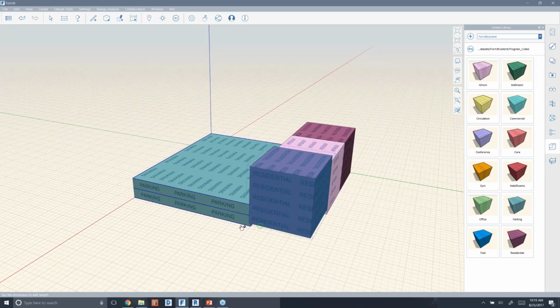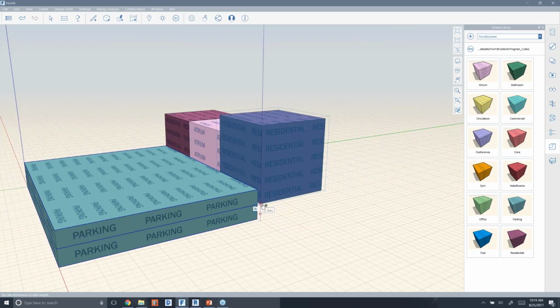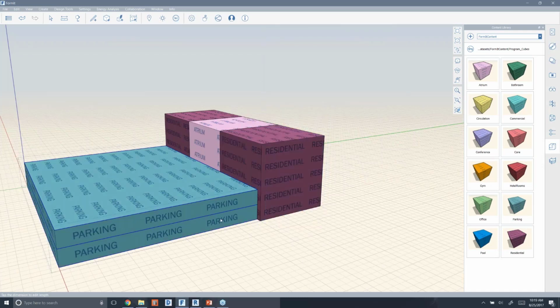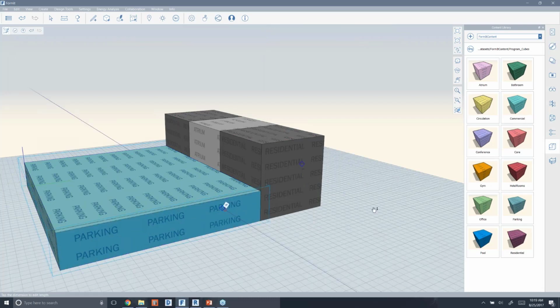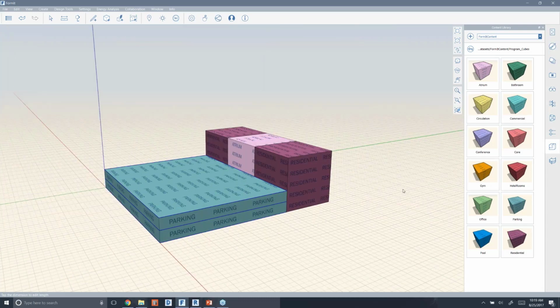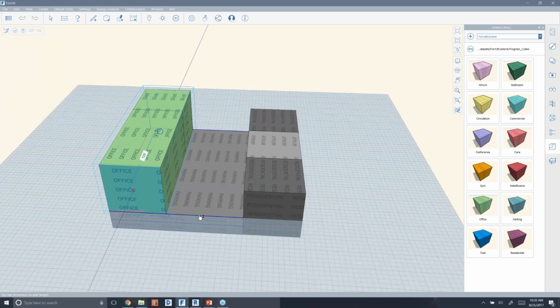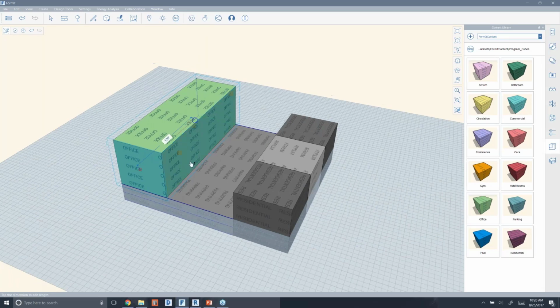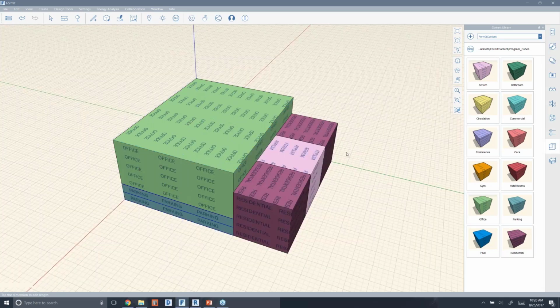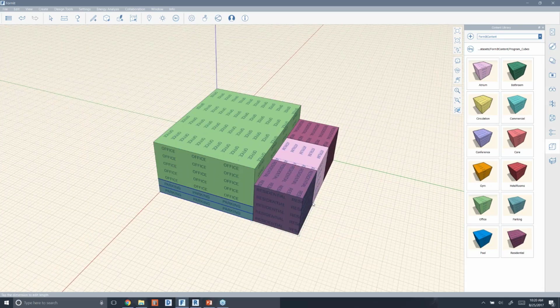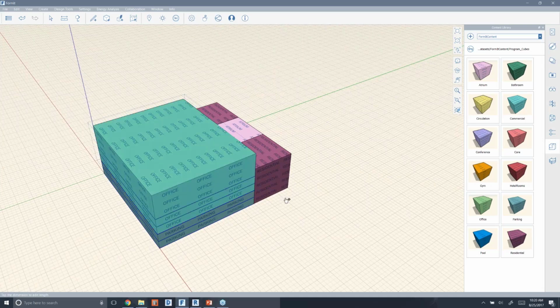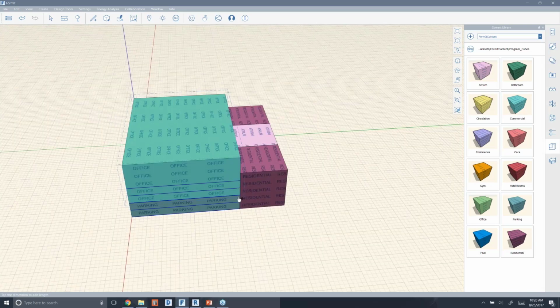Yeah, and if you place something in the wrong spot, then you can use FormIt's other move tools to get things back to where you want them to be. You can continue to drag things and snap them. And I'll go ahead and drop an office cube onto the back of this for a neat multi-use building. A lot of office space. And then I'll go ahead and hit UL to say use levels on these different objects.